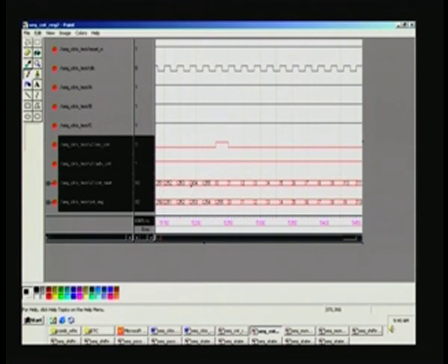So, I think it would be better to have start and end point, that should make it very clear to you. And you can see here the counter reg is 250, 251 and so on, corresponding to 250 it is a pre-increment. So, it is 251, and right at this point of time here you notice after 255 the counter next has become 0, and this counter 255 is appearing only at the next clock edge here.